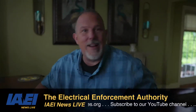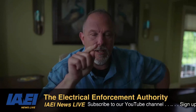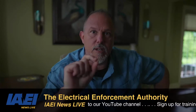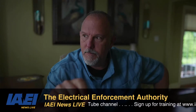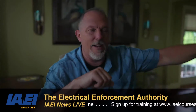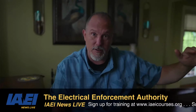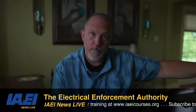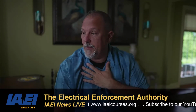And you know what? It's over an hour. So here's what I'm gonna do. We're gonna continue this next week. We're gonna continue this discussion. I did not think 210.52 was gonna be this messy. But I think the 5.5 foot rule does it. For next week, I want all of you to go into your kitchen and measure for that receptacle placement that's on the wall. If it's less than 5.5 feet, then you've met that requirement, in my opinion.